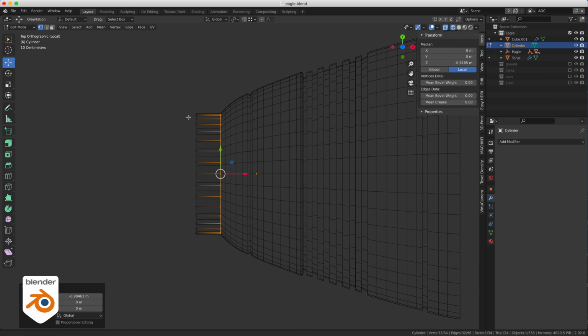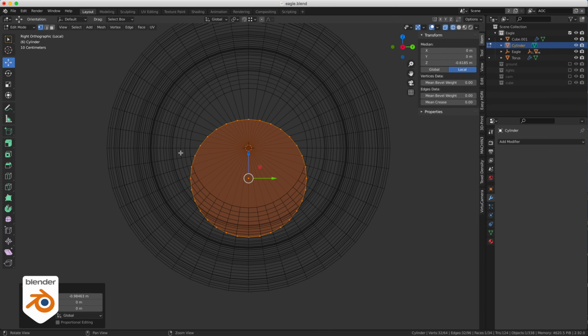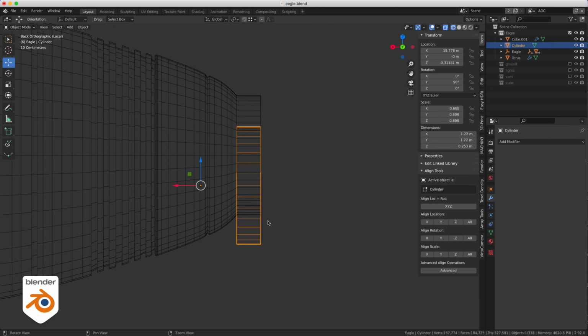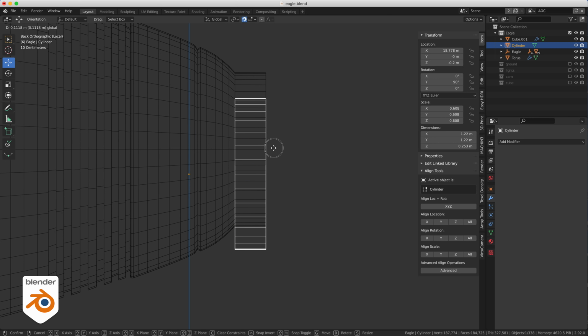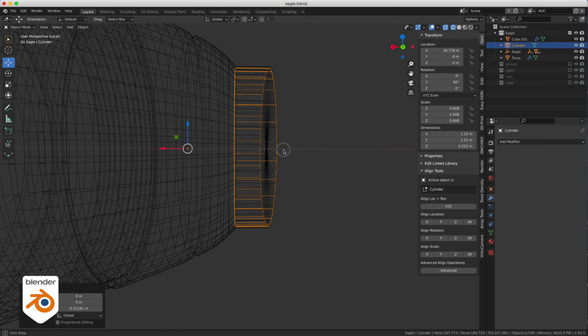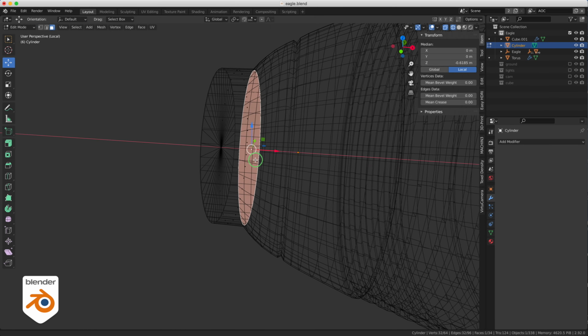And what I did in my case is I made a hotkey that when I press the letter X, it's going to turn on the snap to vertices automatically, and when I release the X, it's going to turn off the snap. So no, I don't use X to delete objects like in Blender by default, and that's why I'm not showing you all the hotkeys I'm using, because I customized my Blender too much.